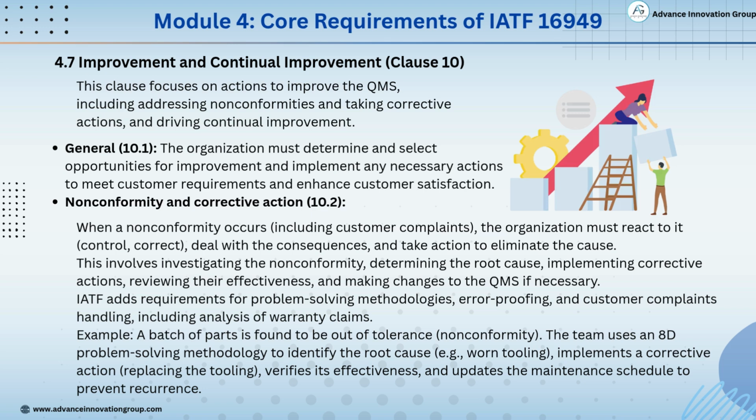Example: if a batch of parts is out of tolerance, the team uses an 8D problem-solving approach, identifies worn tooling as the root cause, replaces the tooling, checks if the solution works, and updates the maintenance plan to prevent recurrence.